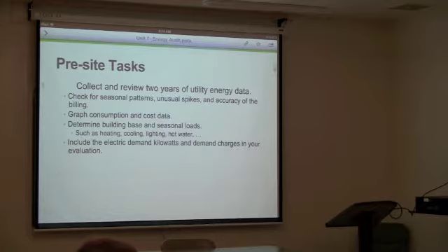Because when you look at the graphical presentation, you would see this is an off-season, and there is no production, or the factory is shut down for so many long hours, but why is the boiler working full-time, 100%? When you go to look, you find that there is a steam trap somewhere that is not working, and it's draining the whole boiler, and the boiler keeps working constantly, basically. So graphical presentation is very important.